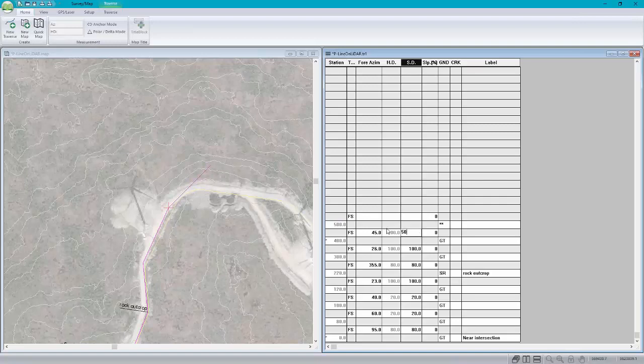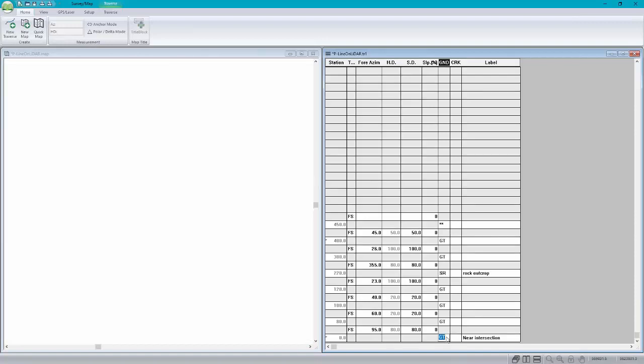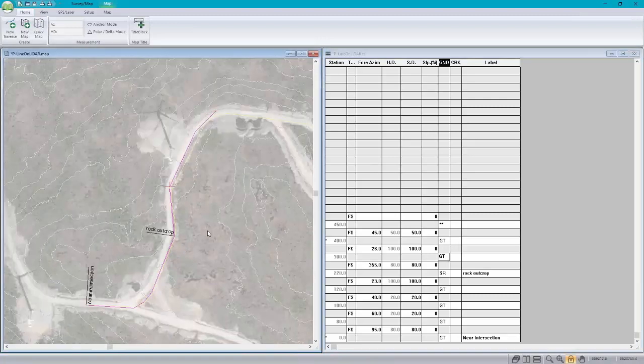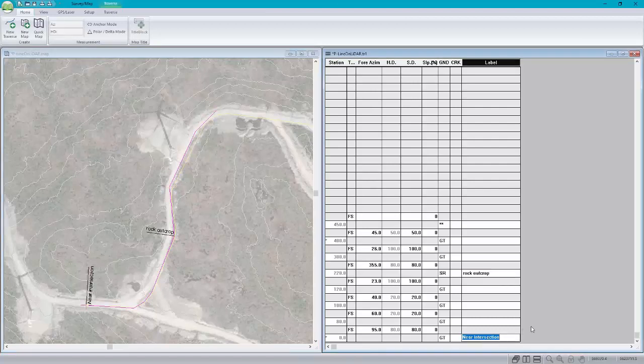just as I would do if there was no lidar data, and survey in the field where I think this thing should go. Meanwhile, picking up information like ground type, where is there a rock outcrop, where is there peat, picking up other information which I can put into comments, and all this stuff becomes a little bit of ground truthing that I can refer to when I go back to do my road design.